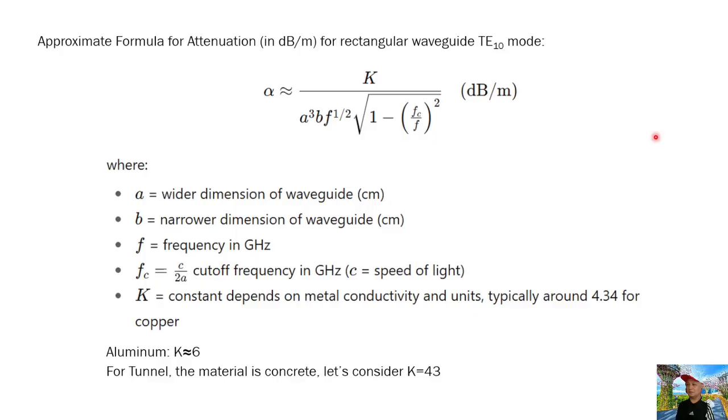And then in this tunnel, we need to calculate the propagation loss. This is critical because there is some story behind this project before I joined to support it. They had some doubts, and the understanding at the time in the team was that in the tunnel, the land mobile radio system could only transmit about 100 meters. So they would need many base stations or repeaters in the tunnel. So this was far over the budget.